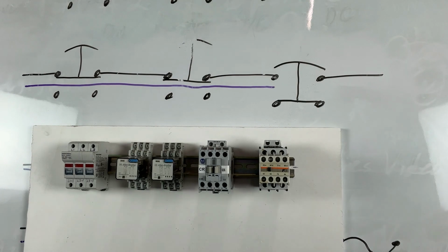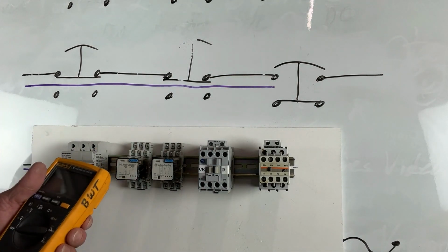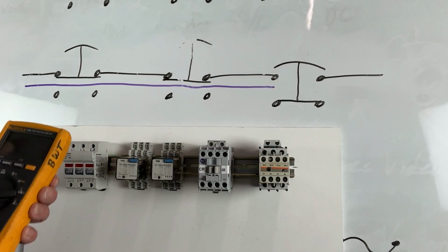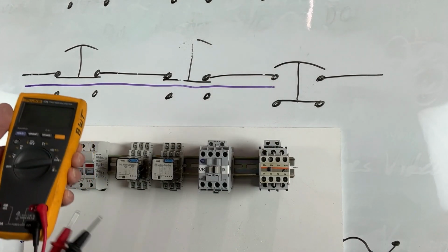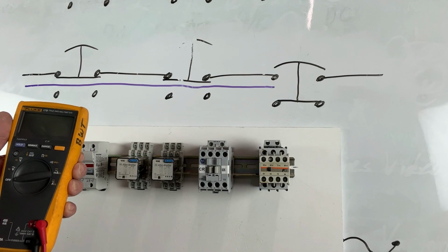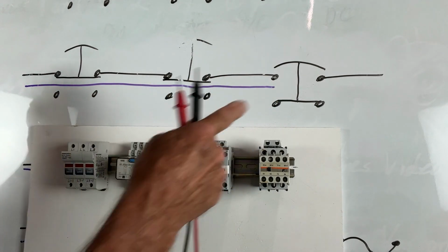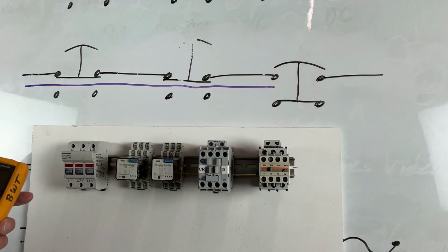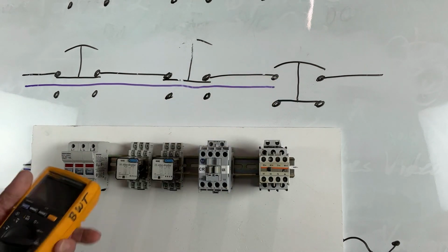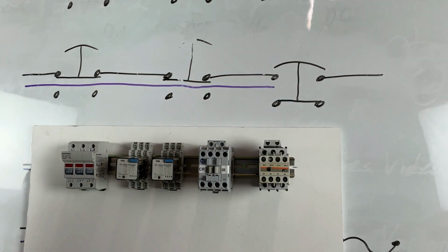And as far as switches go, it's just either on or off. So you just need to know that open is OL, resistance is any value between 0 and OL, and continuity, or a closed circuit, which is what you're wanting for flow, is going to be very near 0. So that's got us on that.